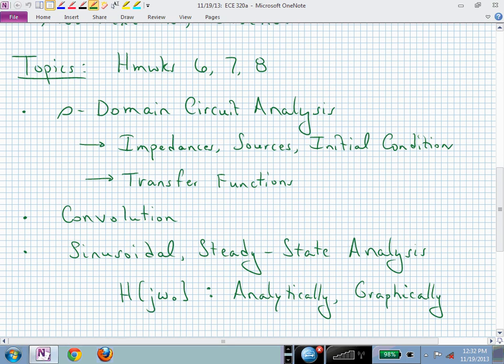What are these limiting values that might establish initial conditions on inductor currents and capacitor voltages, and finding transfer functions? When you're finding transfer functions, what happens with initial conditions? You don't need to worry about those. So you don't have to incorporate initial conditions in your circuit if you are simply finding the transfer function between an input and an output.